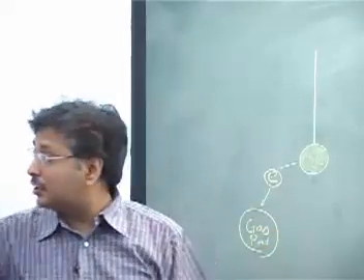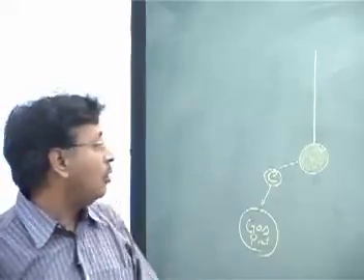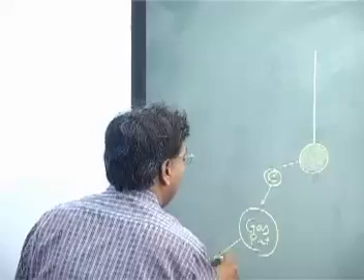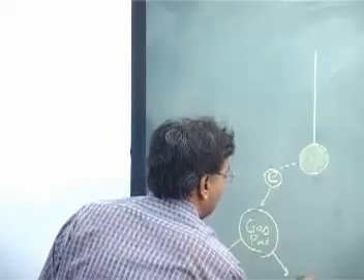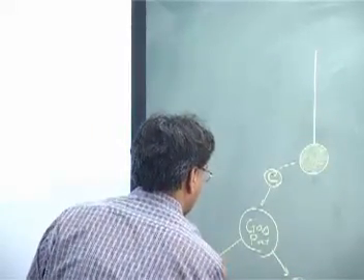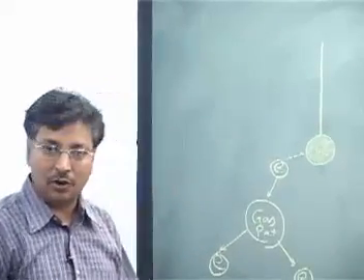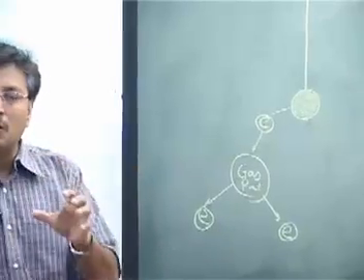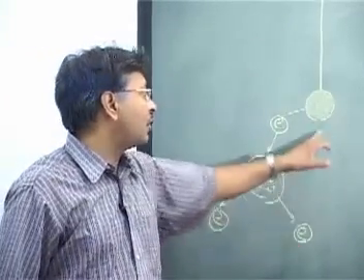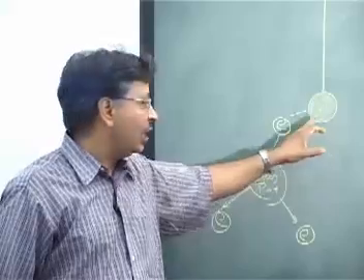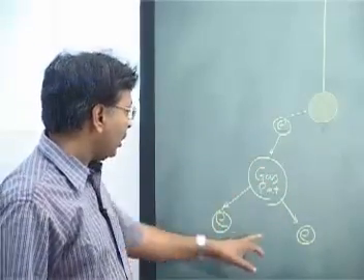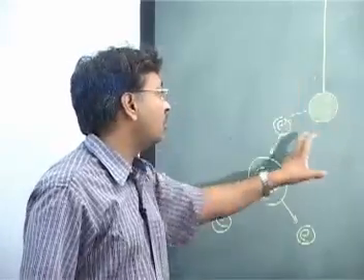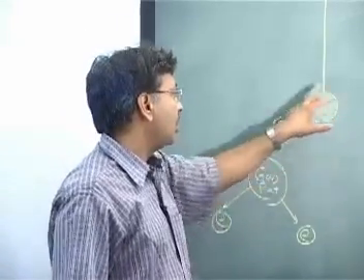Remember that this is happening very, very close to the electrode; we are only showing it in a bigger picture. So in the process this can knock off some more electrons from the gas as they go away. Again, they can knock off more, but as they go away they also lose energy because they are getting far from the electrode, and the numbers will reduce.